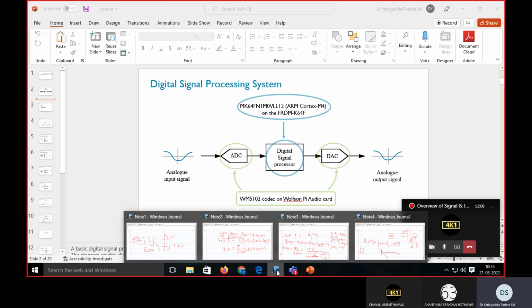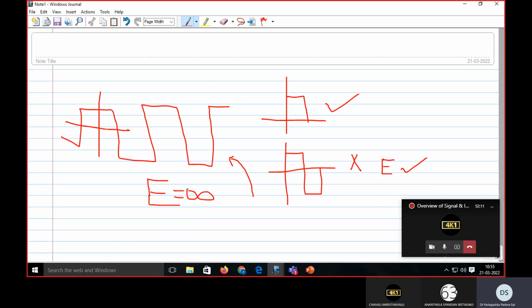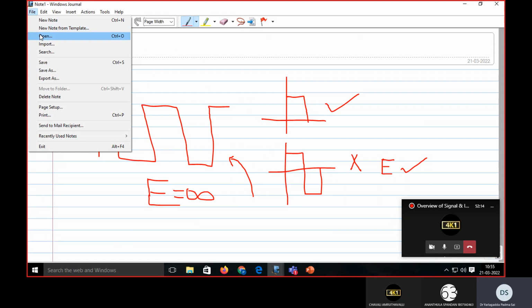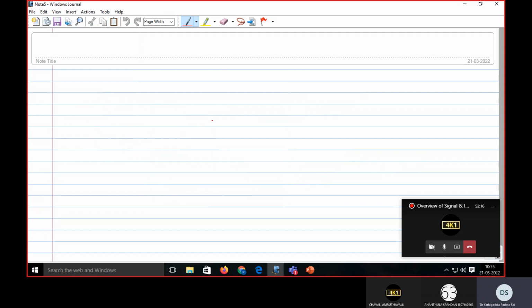When you take the Fourier transform of any signal, according to the definition it exists from minus infinity to infinity. But here we restrict to the band from minus omega m to omega m. Even though the signal has significant amplitude beyond that, I am not considering those points.